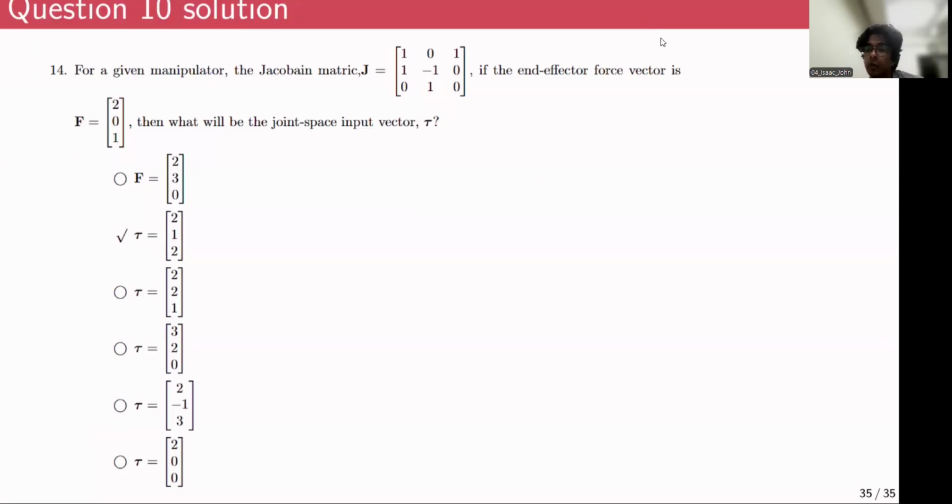How to find Jacobian if x and y are given? All right. So typically, if you have x as a function of joint variables, f1 of q, and y, maybe I'll write it as a function of two joint variables, theta1 and theta2, and y is another function of the same pair of joint variables.